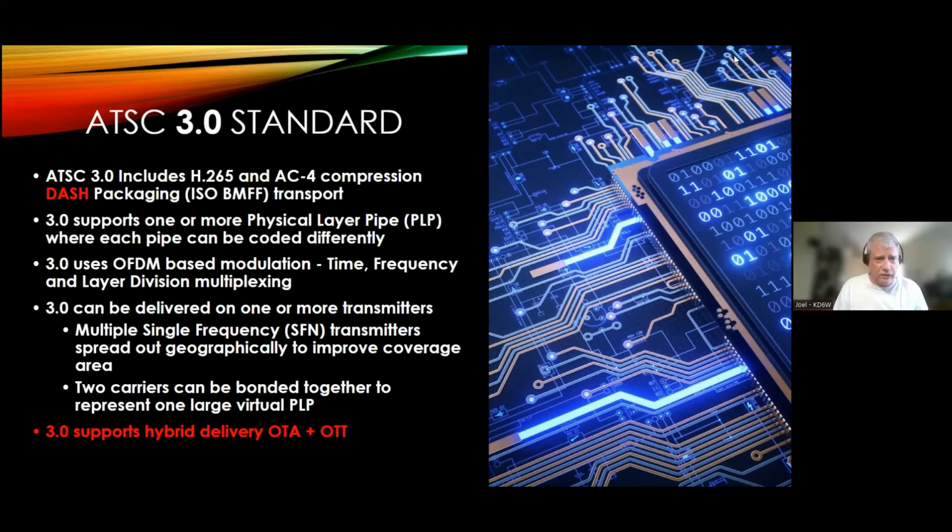They like this technique called SFN, single frequency networks, which means you can have multiple towers all running on the same frequency, but they're phase aligned so that all the transmitters emit the same bit at exactly the same time. And so it creates a certain pattern which doesn't interfere, unless you live in one of these particular places, in which case they try to null those places out. But the signals become additive. And so with more transmitters, you get a better coverage pattern. So it's of great interest to them. This SFN is a big thing.